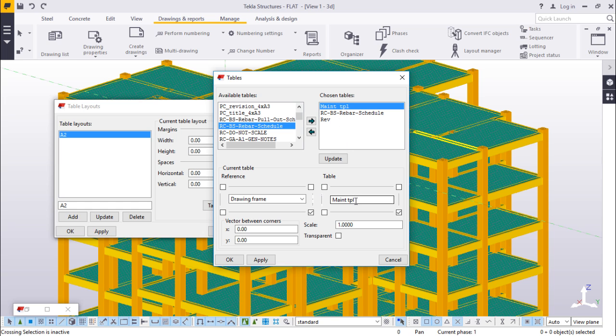Now we'll start with the main title block. We'll sit right at the corner on my right of the drawing frame. You check that and check this. Then if I go to revision, I'll check my main title block, that corner and this corner, mesh up with the bottom of this revision. That's perfect. I'll just apply. Now when I highlight RCBS standard rebar schedule, I'll click that.